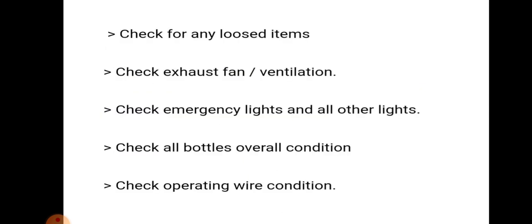So what are the general inspections carried out in the fixed CO2 fire extinguisher room? Check for any loose item. Check that the exhaust fan and ventilation are proper. Check all emergency lights and all other lights. Check all bottles' overall condition.